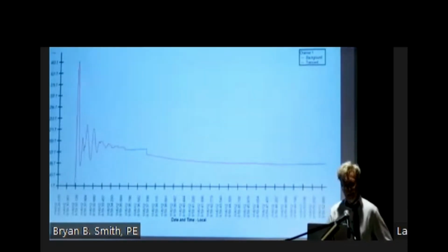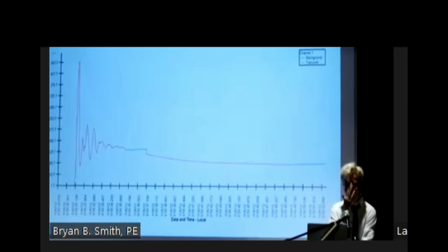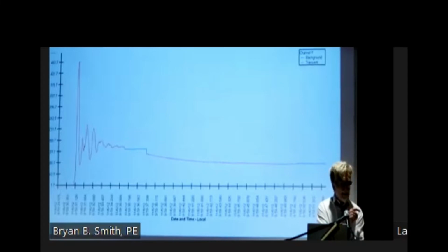When we're designing a system, it is also very critical to look at the pump curve that you designed the system on. You're like, well, what do you mean? We've been talking about pump trips. Well, what if I'm starting up a vertical turbine pump? Should I be concerned with the startup surge? And it's like, yeah, of course. And in the software, it's really difficult. How do you model that? You just can't, because I've got to be in steady state to look at that transient event or the change in velocity in the system.